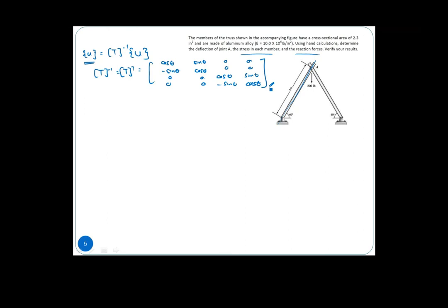But then because this is a simple two members, or two elements, so probably if you look into this particular member itself, this is 60 degrees, this is our node 1, this is our node 3, right? So we have a u3y, which is equals to negative 2.087 times 10 power negative 4, right?